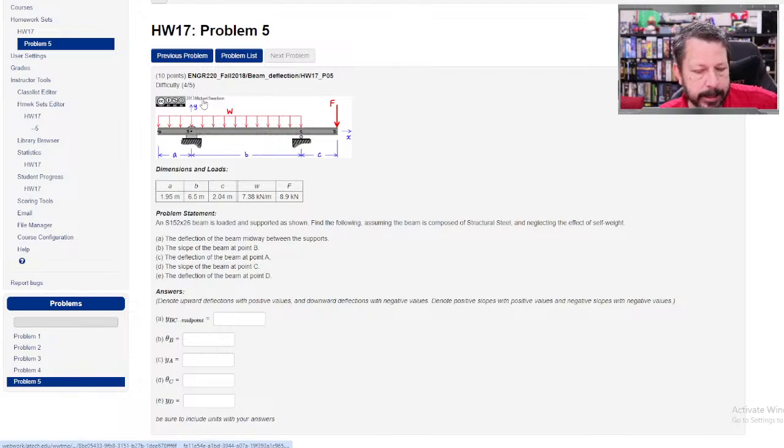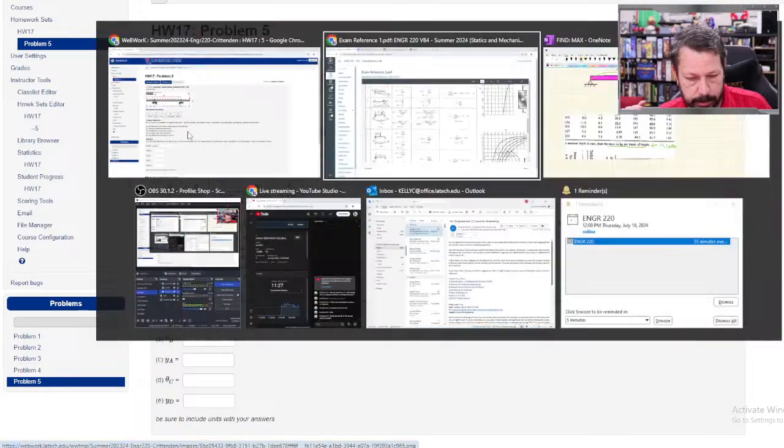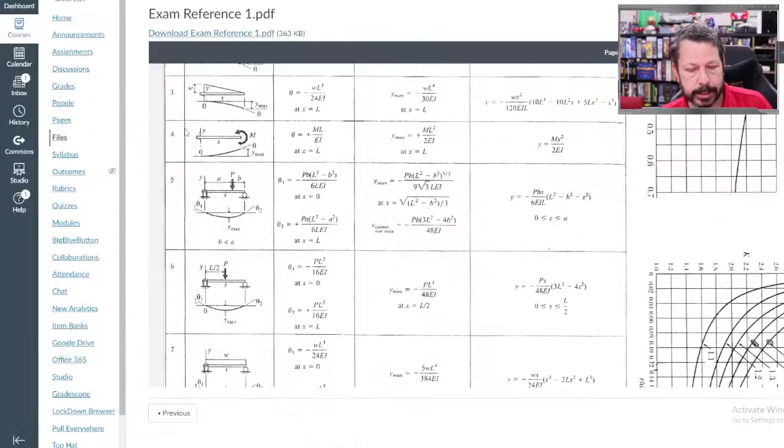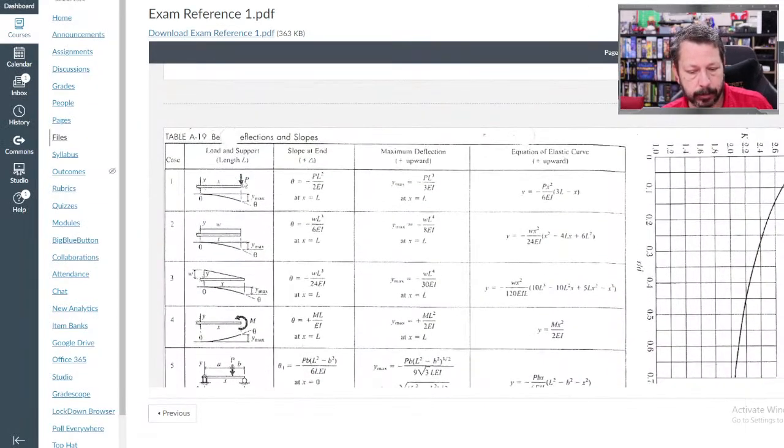This is the one I was thinking of where the origin is not at the end of the beam. So the origin's at B here. So basically AB is a little cantilever section of its own, and you kind of have to mirror the charts here, where P is off to the left.